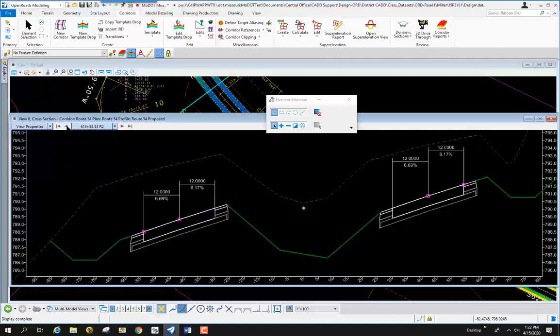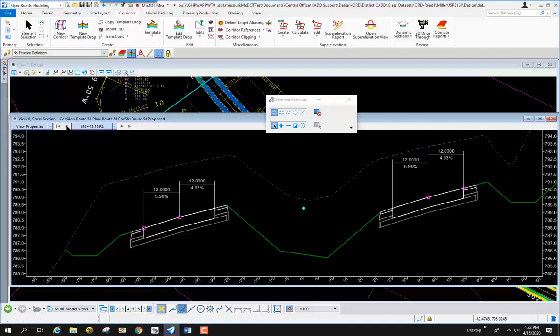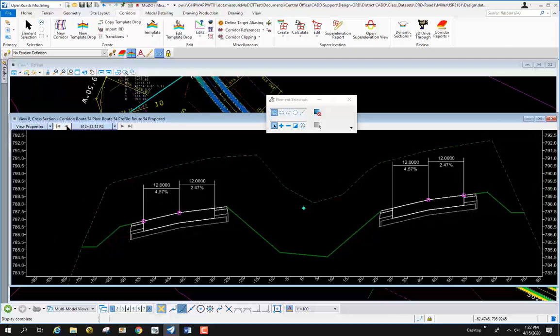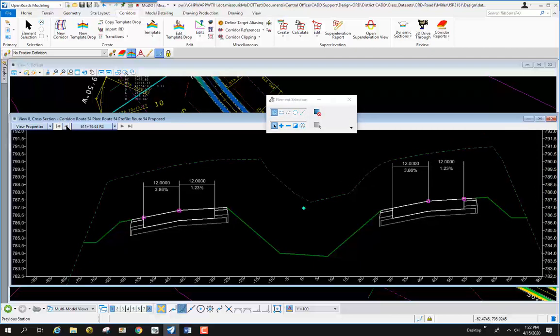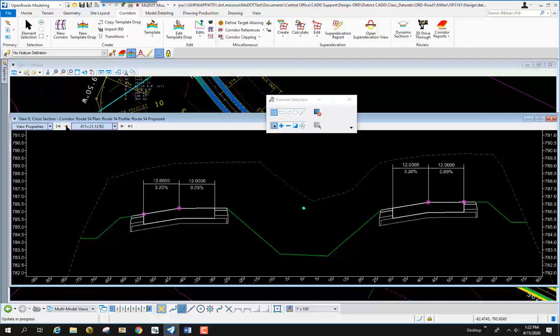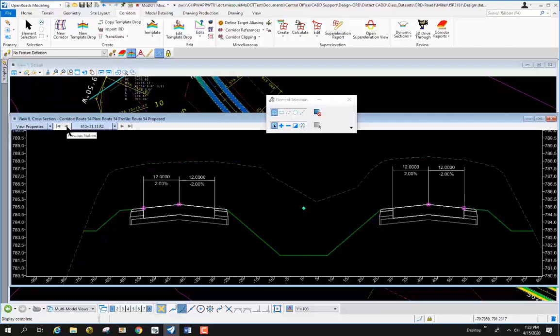And so if I continue to go back, you can see that we're super elevating back down to a 2% slope, or normal crown, and you can see we're at the zero crown location there, which is the BB section. It's 0 on this slope and 0 on that one, and you can see that we're rotating about the inside edge on both of these. And so now when I go back a little bit further, you can see now that we're at a 2% slope, or a normal crown, where we're going up 2% and then down 2%.